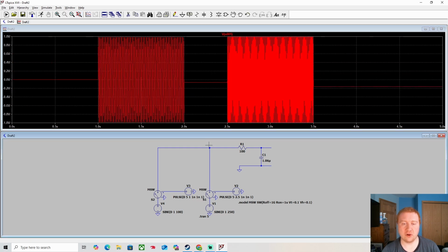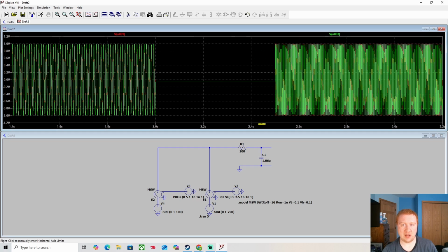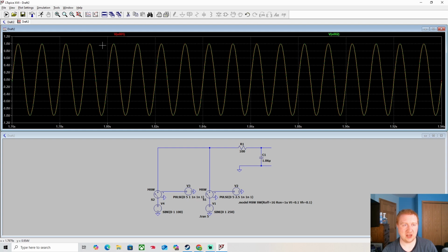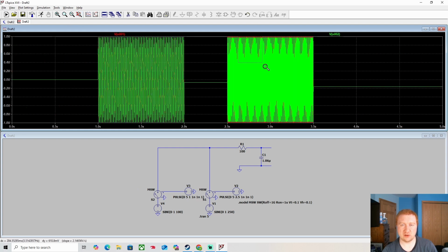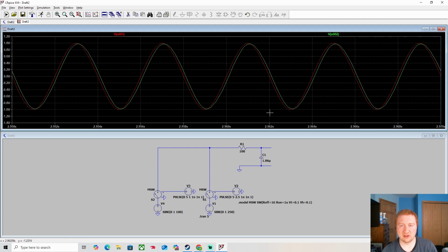No, sorry. Before the filter, it's always going to be the full signal strength. This is before the filter, before the resistor and capacitor, right? Between this and ground, right here, is the 1 volt signal. So this is the unaffected signal. If I measure the output, the amplitude is going to be very identical for the 100 hertz. It's almost no change. But on the 250 hertz, you now see, it's very subtle, but it is less.